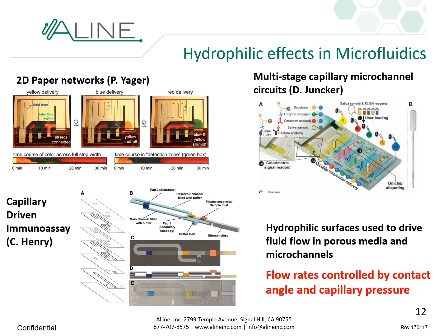And what is very important is that the pressure that is driving is the same pressure we were seeing before. So the flow rate is actually controlled by the contact angle and the capillary pressure. So any variation in there is really going to impact the final result of these experiments.